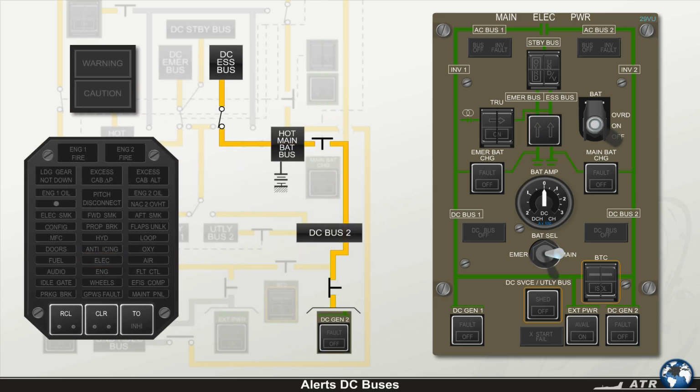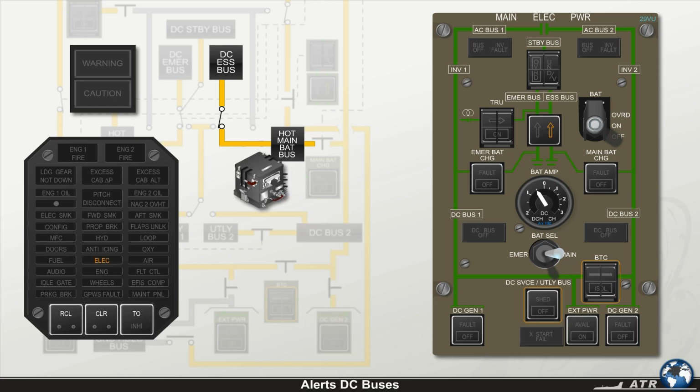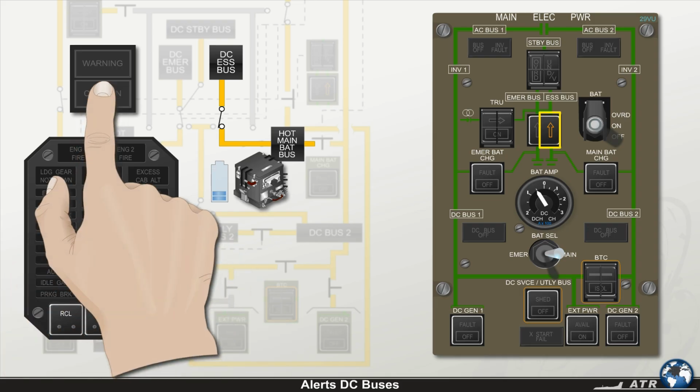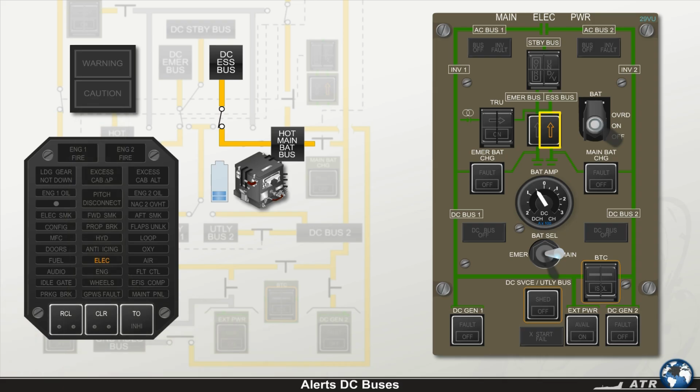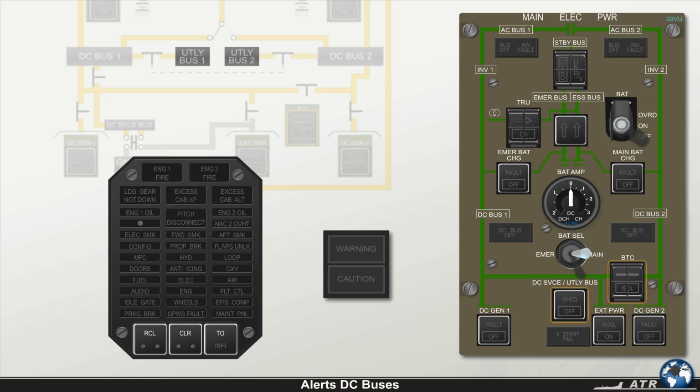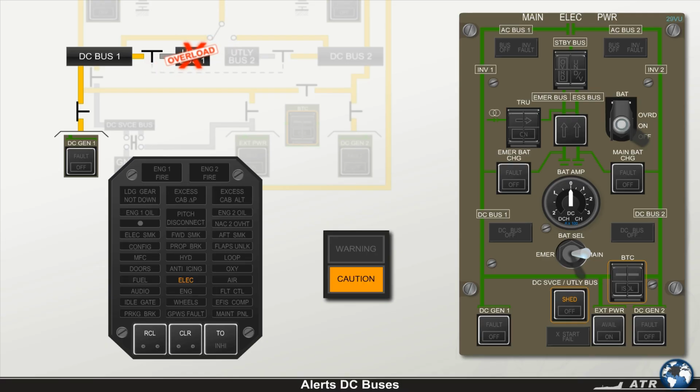If a similar situation occurs involving the main battery, the CCAS is also activated, but the right arrow illuminates amber in the emergency supply indicator. This situation alerts you that the main battery is being discharged. If one of the utility buses has been shed by the bus power control unit due to an overload condition, the CCAS presents you with the following information.